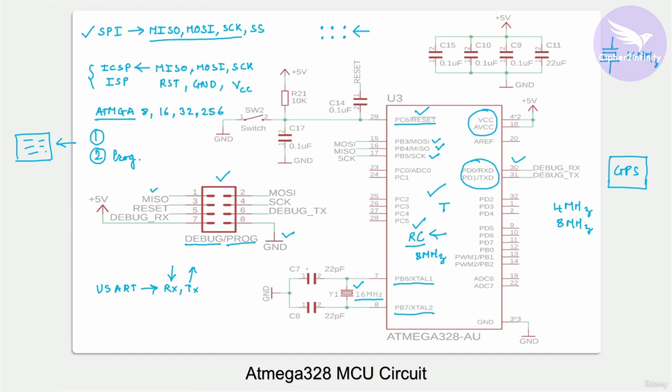After that, you can see here, these are the load capacitors that we have connected around this crystal. And these load capacitors are part of this oscillator circuitry. You know, these days modern microcontrollers come with a Pierce oscillator. You can read about Pierce oscillator circuitry on Wikipedia or on the internet. So these two capacitors and this crystal are part of the Pierce oscillator circuitry.